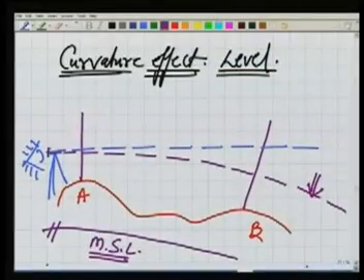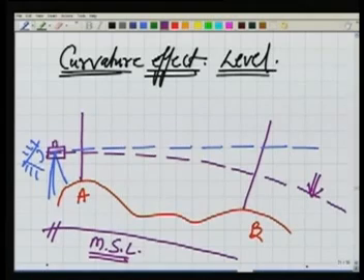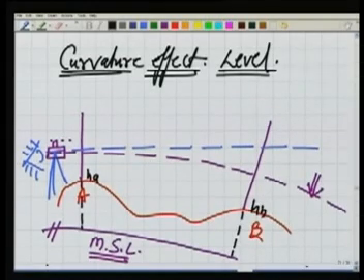But we cannot do it. We cannot see along the level line. We cannot see along the level surface. That's not possible. What we can do best, we can establish a horizontal line of sight, as we have seen. So what we are establishing by our level, the level is kept here with the bubble tube. We are establishing this horizontal line of sight. So it is obvious here. As you can see, the RL of A is HA and RL of B is HB from mean sea level. Okay.